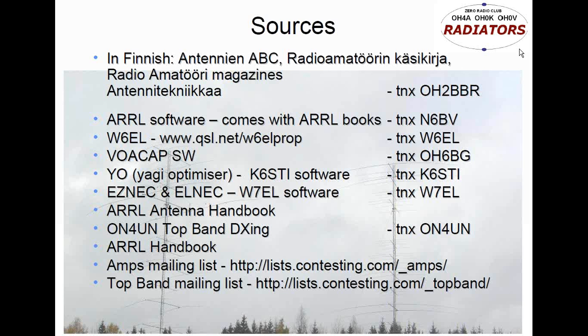I have a 2-element Yagi on 80, but I'm benefiting from this FO0AAA antenna. If you go to Google and put in FO0AAA receiving antenna, I think it will guide you to construction details at the necessary level, so you can duplicate what I have done. I have an array of 6 of those antennas on my property, and I can switch them. Typically I can hear maybe 20, maybe 30 stations on 160 meters that I wouldn't be able to operate with my wire antennas or transmit antennas. So this receiving system increases my 160 meter score by 10%, and I'm very happy with that.